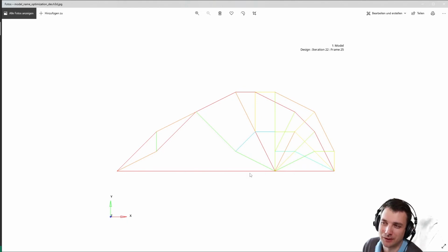You cannot see it directly here, but I'm assuming that this is it. You have a starting point here, and the max beam length was 8. So the first element was put in the driving lane up to here. And as you have just loads on the driving lane nodes in between, this will get this asymmetric design. But I like it. I find it quite beautiful.